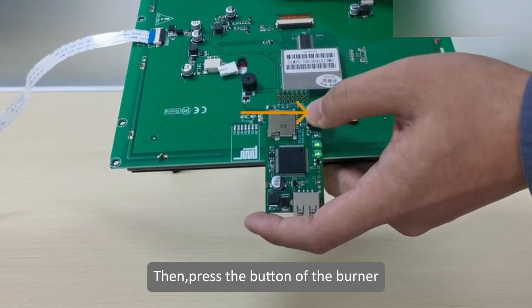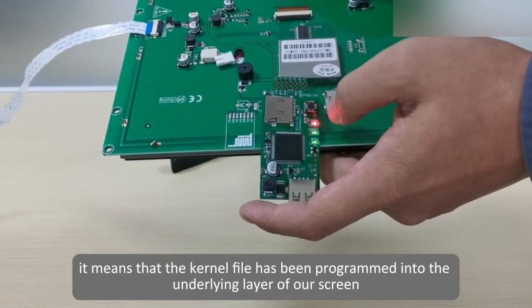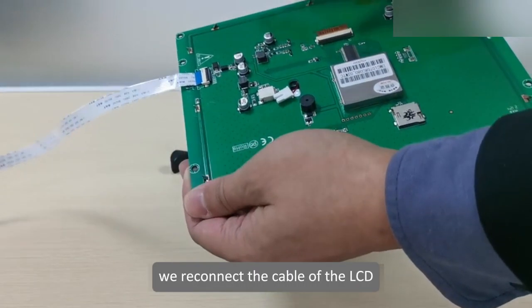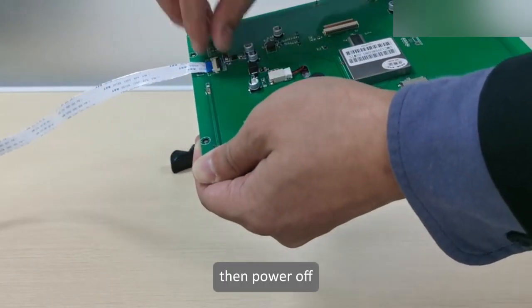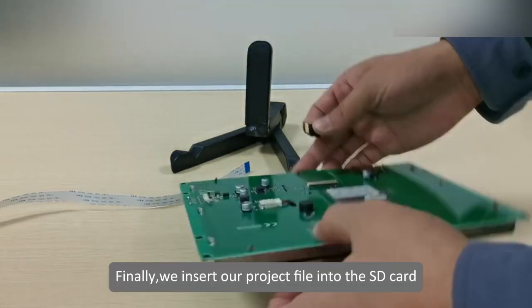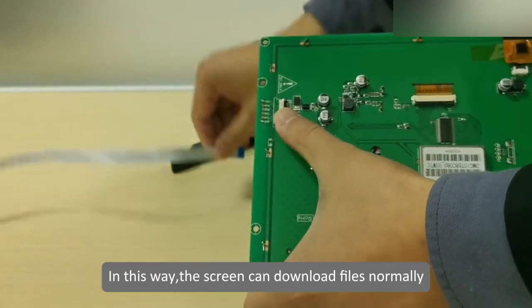Then, press the button of the burner. When our red light turns on, it means that the kernel file has been programmed into the underlying layer of our screen. Next, we reconnect the cable of the LCD. Then power off. Finally, we insert our project file into the SD card. In this way, the screen can download files normally.